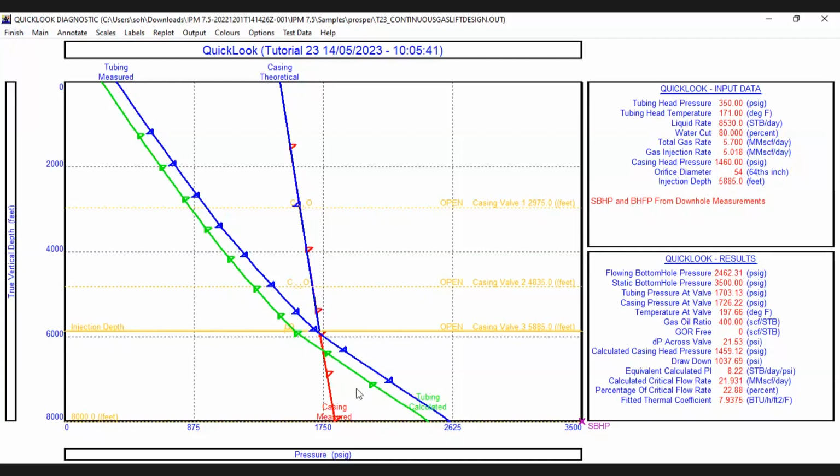Yes, but the reason for changing the variables is that we don't know exactly what is going on. For the tubing size, we know exactly that the tubing size is 3.5 inches. If you go back to the downhole pressure, the changes from the downhole to the surface are consistent with the measured one.